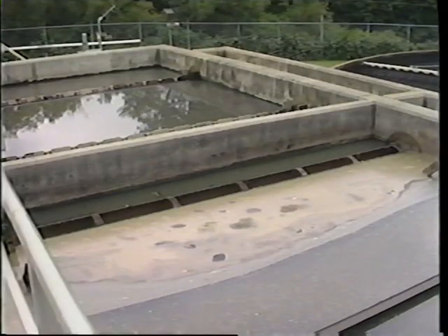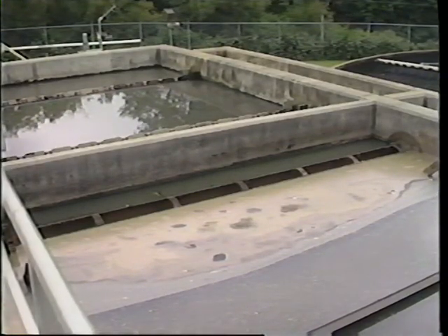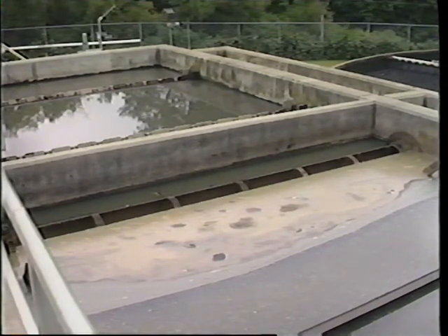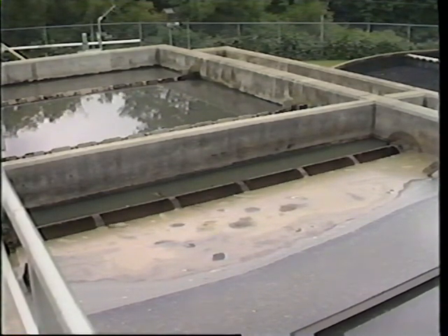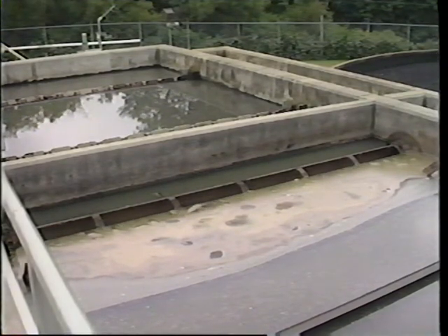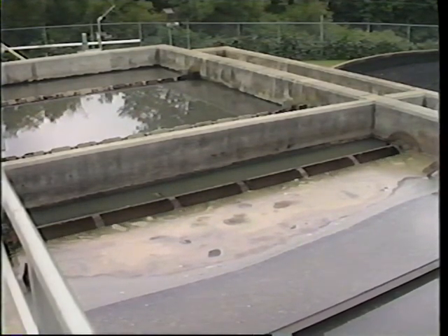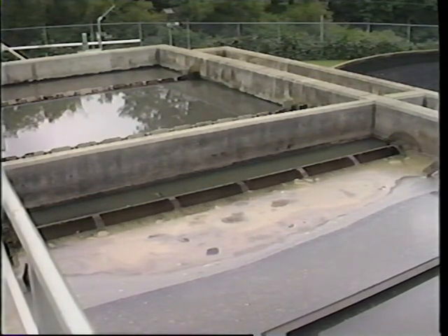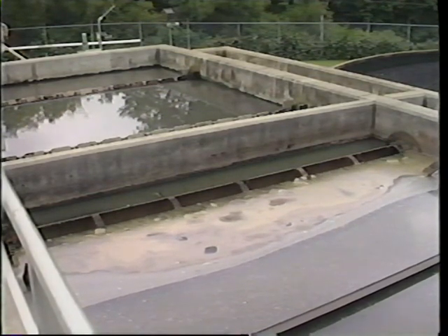The slow flow rate provides for an adequate detention time, which is the amount of time the wastewater needs in order to receive effective treatment in the clarifier. So quite naturally, the longer the detention time, the greater the solids removal potential. However, too long a detention time can result in septic conditions that could adversely affect downstream treatment processes.